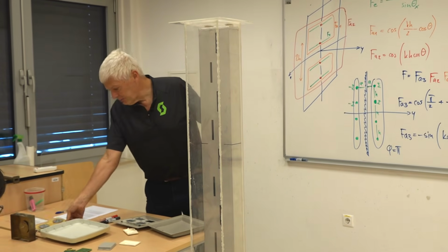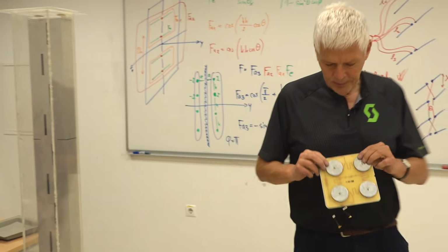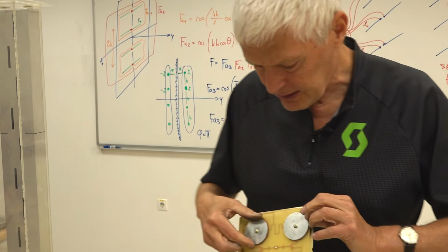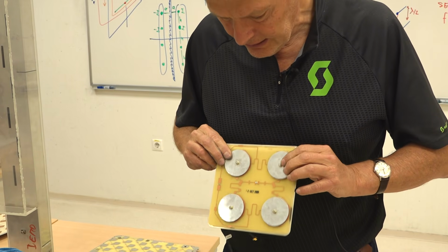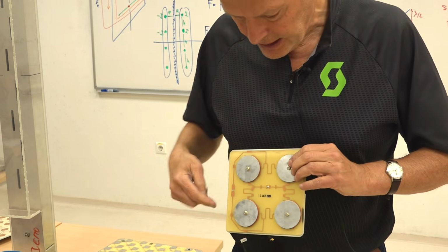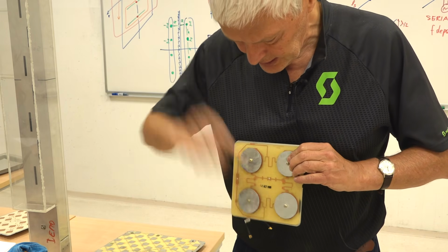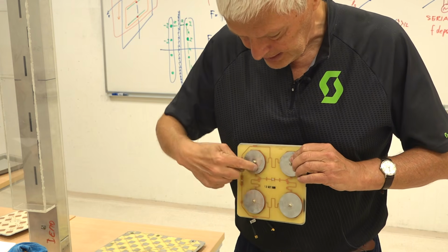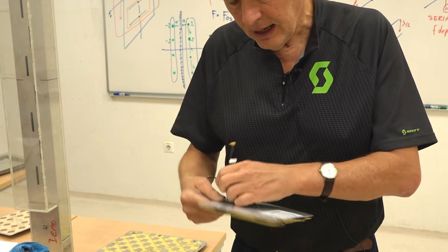You may have both polarizations also on such an array here. You see, this array has 4 patches, but these patches have an additional disk, an additional parasitic element here to increase the gain. An element of 4 patches fed from this point for horizontal polarization and fed from this point for vertical polarization. So this is a trick to have both polarizations out of the same array.